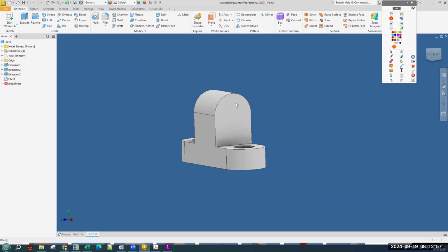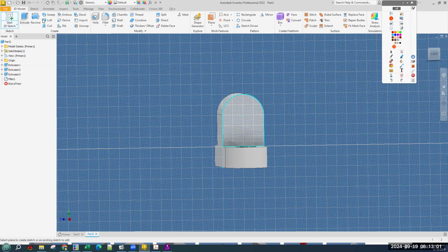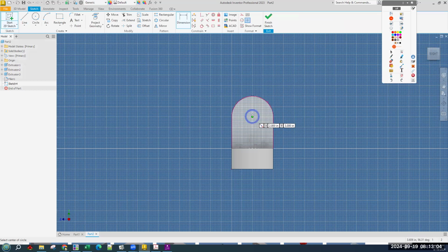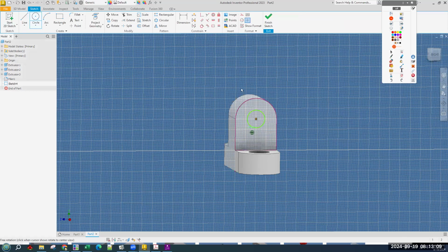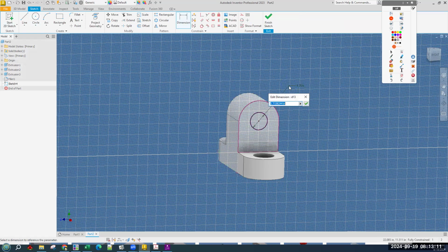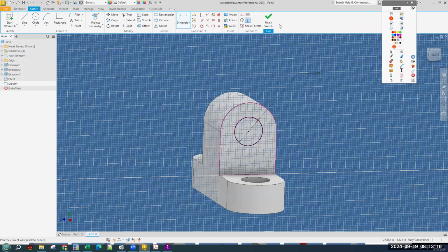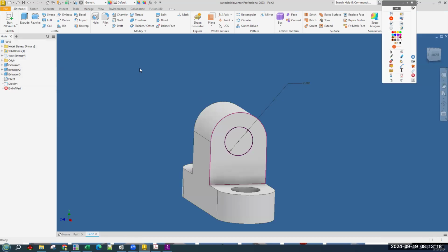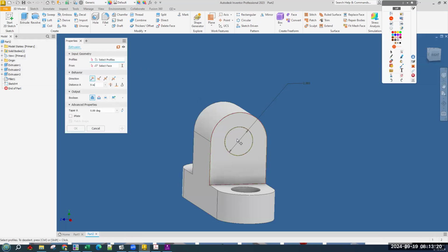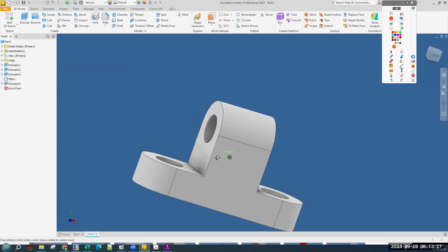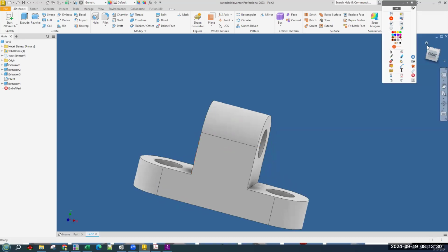Okay, and then the last part, just that through hole. We'll start a sketch here. Get a circle and center point there, and dimension it to 2. Finish sketch and extrude. Choose the circle we made, switch it to cut, and through all just because, and hit OK. And there you go. There's number 12.